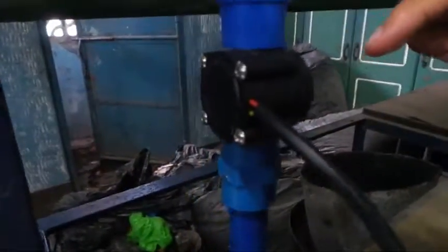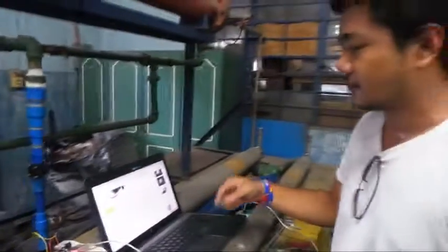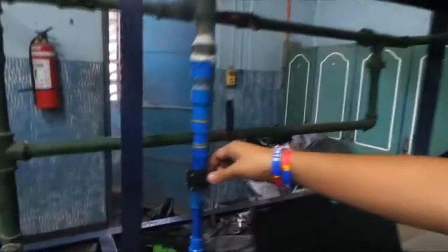It consists of a plastic valve body, a water rotor inside, and a Hall effect sensor, which is also inside. When the water flows through the rotor, the rotor rolls. Its speed changes with different rates of flow. The Hall effect sensor outputs the corresponding pulse signal. The pulse signal is a digital signal. This one is suitable for our project. That's why we use the sensor.